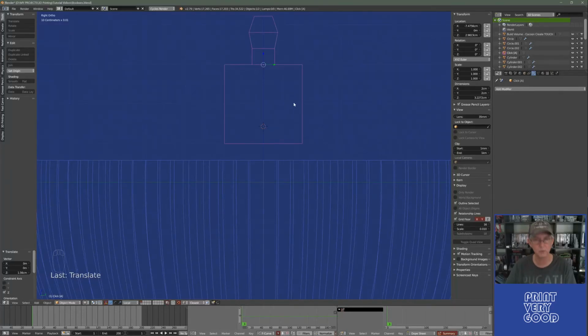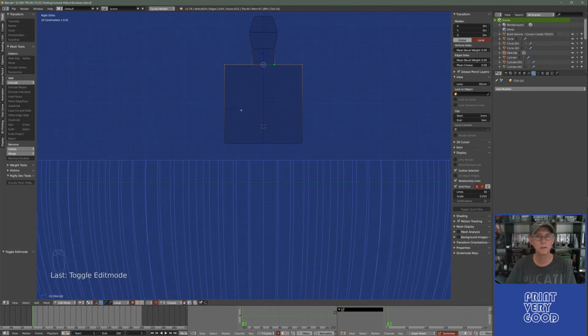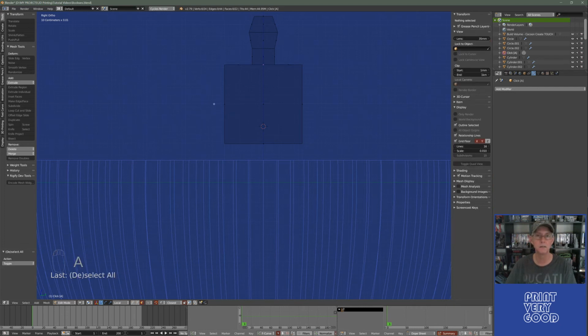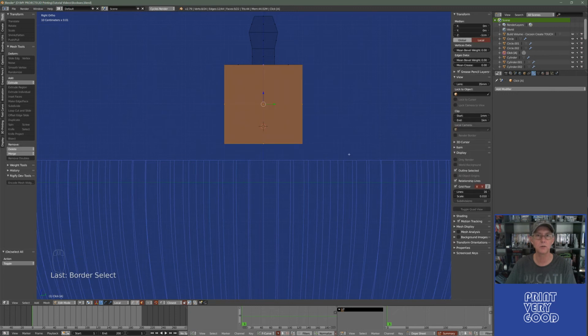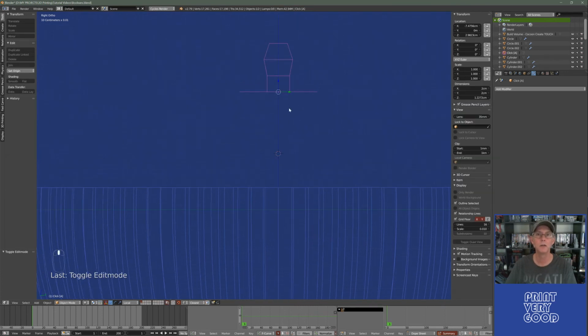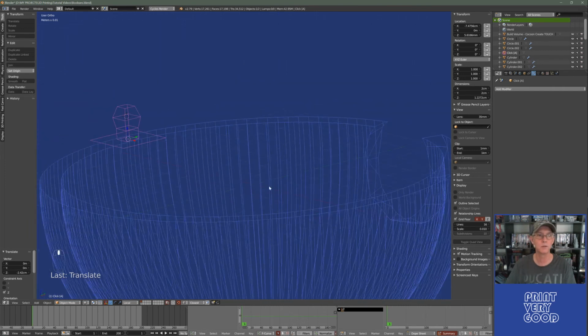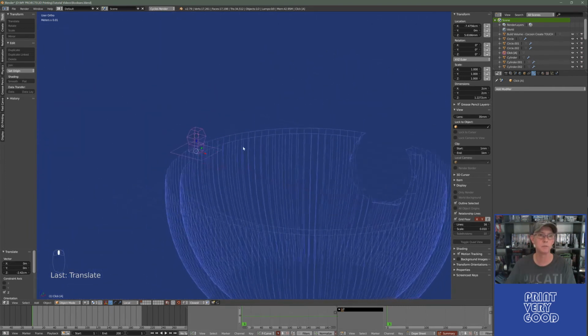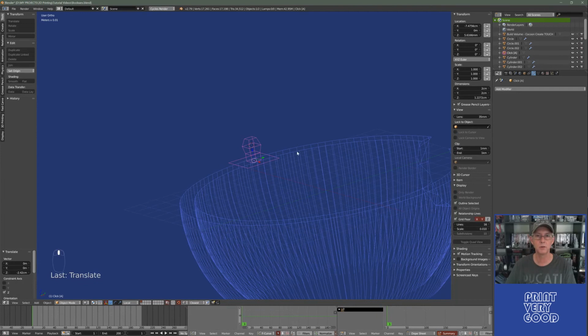In this case, what I would do is select my object, take it back to mesh, go to faces, and I'm just going to press A to deselect everything, B, do a box selection around the faces I want to delete, and press delete and faces. So now we have an object which has no geometry down here. This is the bottom of the object. So now if I press G, Z, boom, it's snapped to that point that we want to snap to. So those two edges are perfectly aligned.